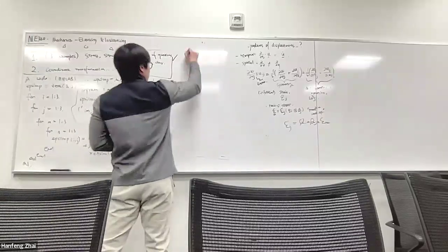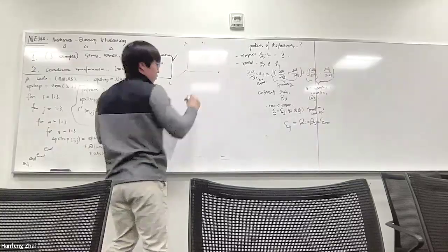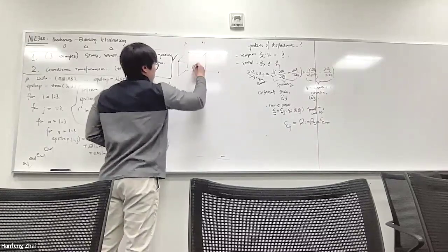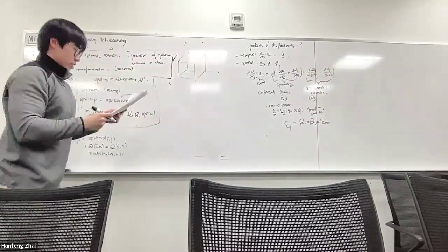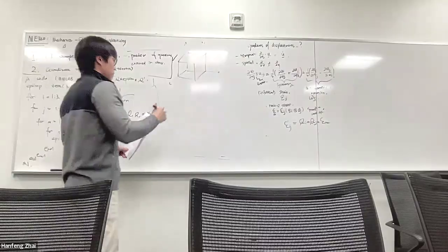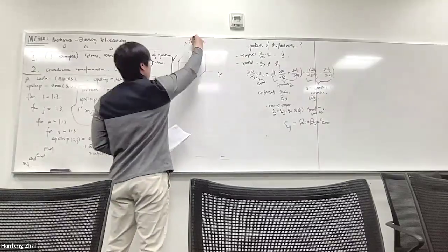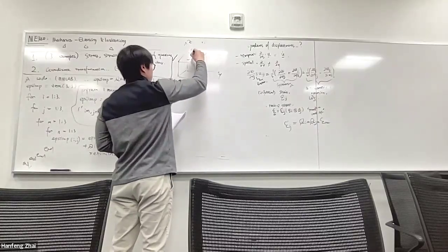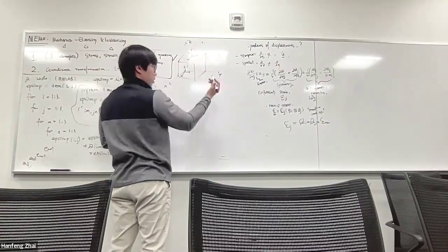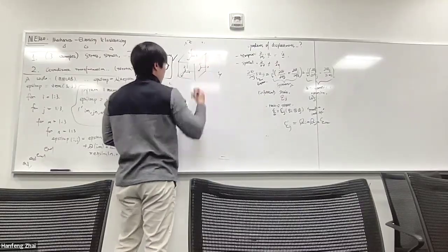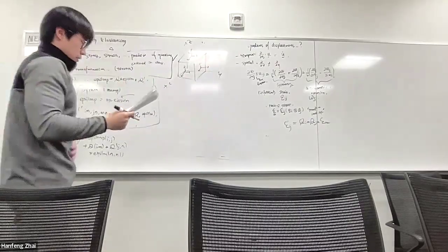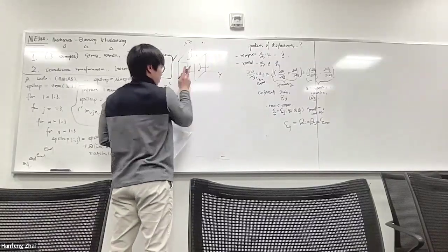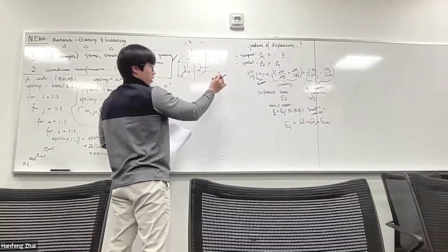What about stress? We want to properly define the stress tensor. So there exists this elastic body on the coordinate system x, y, z, and we have 6 surfaces, and on each surface there are 3 stress components in 3D. Let's say this surface is in the y direction, or the 2 direction.